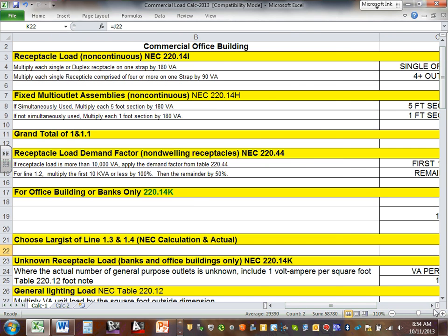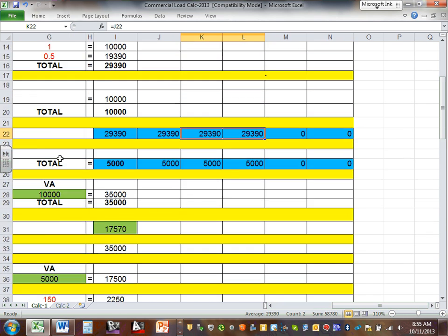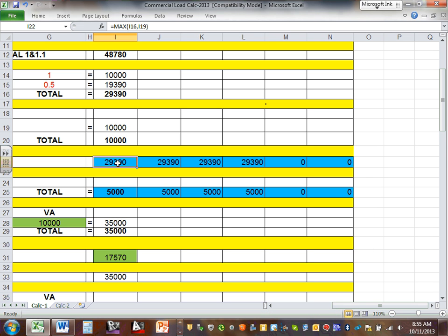Okay. Any comments, guys? Any questions up to the receptacle load? Can I have thumbs up, thumbs down in between? No? Good. So this load is your receptacle load. It will be seen by the main panel and its neutral, by the receptacle panel and its neutral, and it will not be seen by the lighting panel or its neutral, right? Because it's a receptacle load.